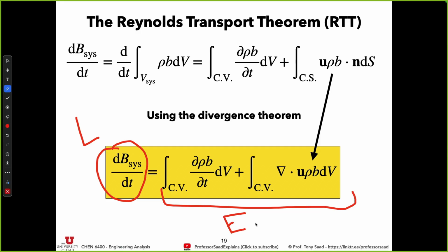And this works like, it's mind-blowing that this works magically. You don't have to even specify what the control volume is. All you have to say is that to go from a Lagrangian form, I just apply this theorem and I write everything in an Eulerian form. Go from the Lagrangian form of the conservation law. All I have to do to convert that derivative on the left-hand side of the conservation law into these integrals. And now I can work in an Eulerian form.